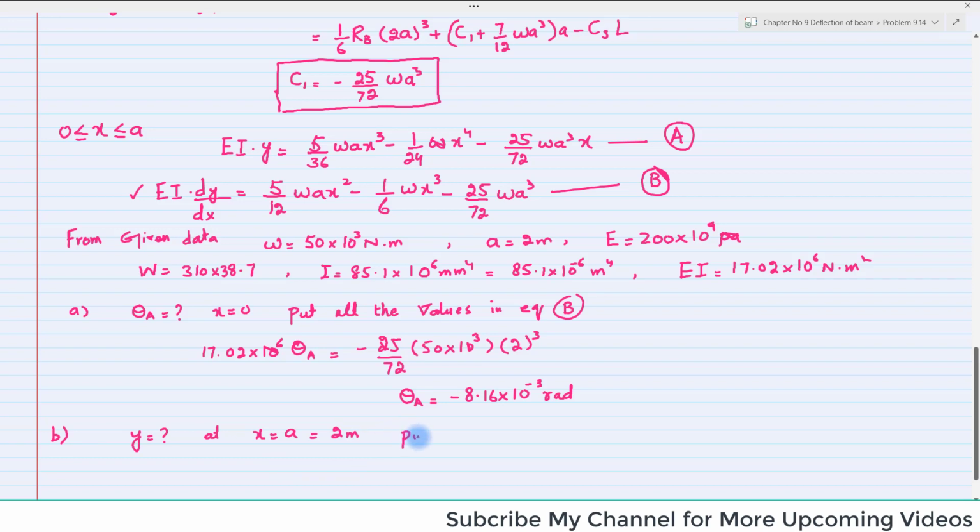So put all the values in equation A. When you put x equal to a, EI, which is 17.02 into 10 raised to power 6, times YC, because the deflection at point C is YC, equals 5 over 36 W A to the power 4 minus 1 over 6 W A cubed minus 25 over 72 W A cubed.